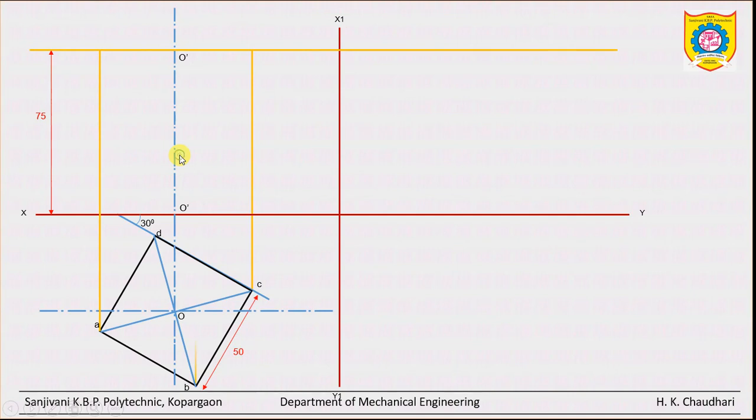This is the axis. Now draw the projection from point B in this way and similarly from point D. So now see, point B means edge B is in front, edge D is at the back side. Edge A is the left side and edge C is the right side. So label them first, similarly on the top surface.